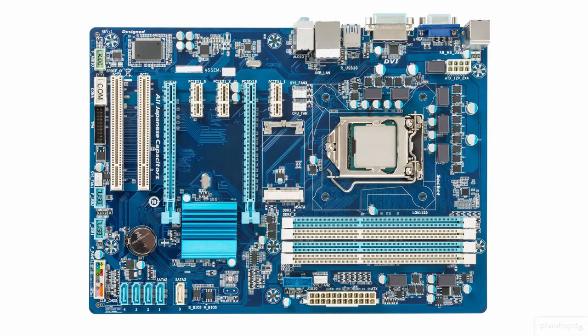Once again, I want to show an ATX motherboard, this time calling out various power interfaces on the surface. First of all, you see the ATX connectors. These are the primary power interfaces that link the motherboard to your PSU. You may not have the smaller one, but you'll certainly have a 20 or 24 pin connector, very similar to what you see at the bottom of this particular motherboard. And these ATX connectors, like I said, are very important because they provide power rails or collections of motherboard traces to all other components on the motherboard.